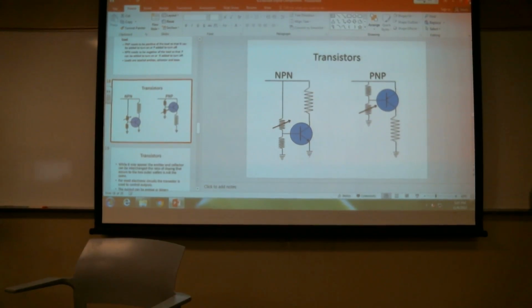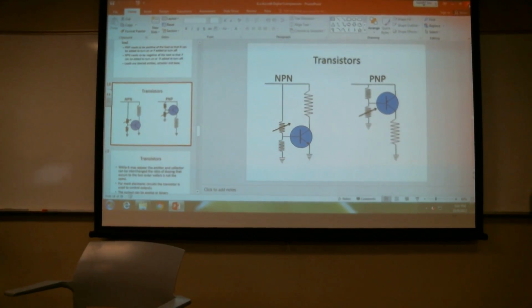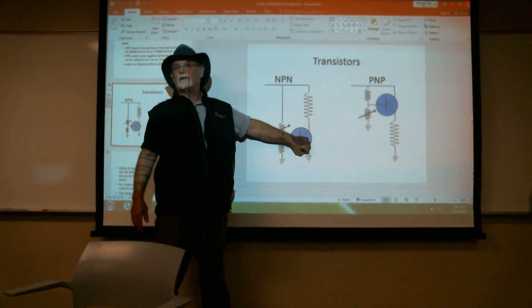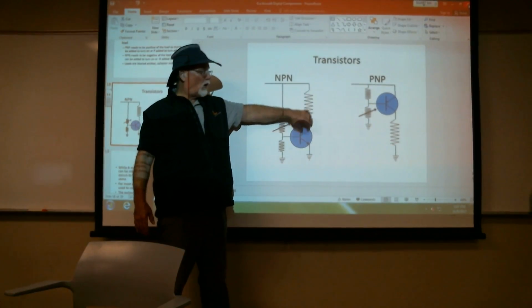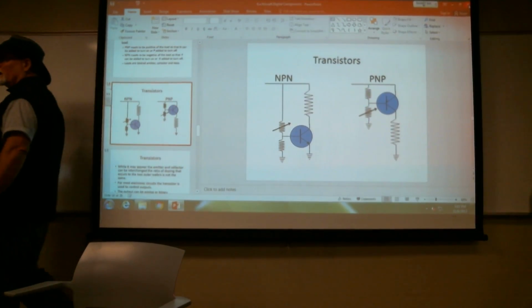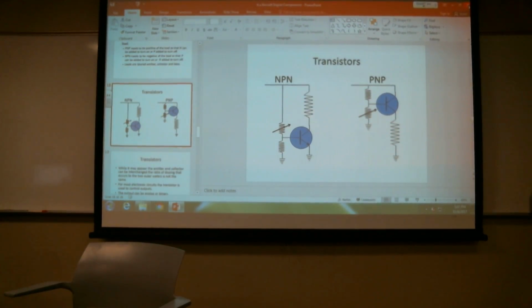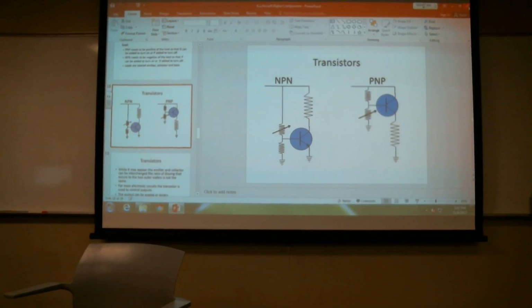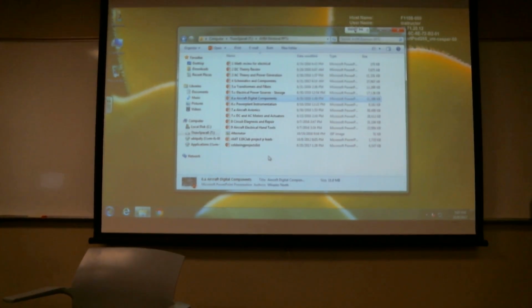On the other hand, if it's like a field regulator that's either switching on or switching off, when it's switched off, there's no current, so that guy doesn't get hot. When it's switched on, all the current's going through there, but there's very little resistance, so it doesn't get hot. It does get hot from the current going through it, but it's not dropping any significant voltage, so it doesn't get nearly as hot. When it's somewhere in between, it's got a lot of current going through it and a fair amount of voltage drop, so it gets a whole lot hotter. And we will in fact design the transistor very differently for switching versus analog use.